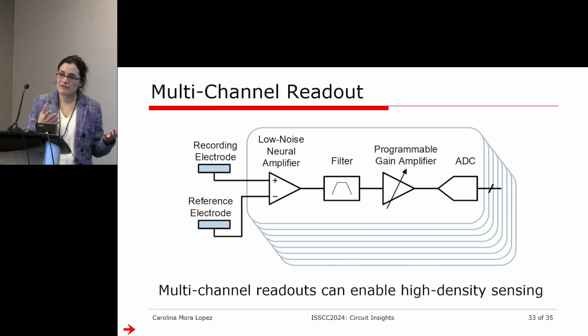You cannot have a chip that is very large, and you also don't want a chip that consumes a lot of power. For an implant, you may want to power this with a small battery or an implantable battery that you don't want to change very often. So we are talking about levels of power here that need to be really very small.